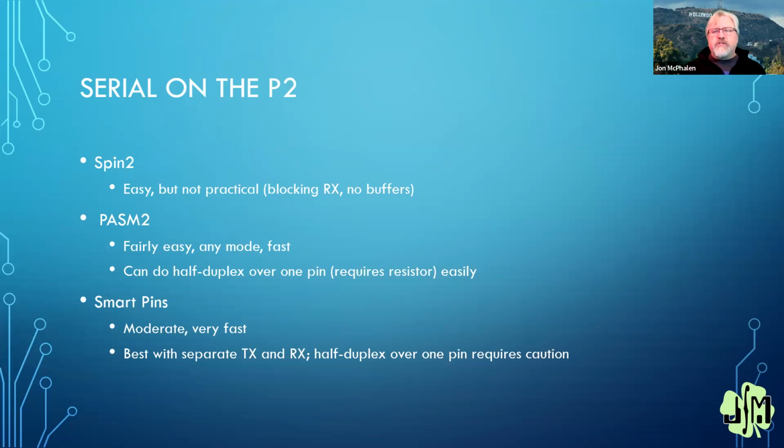It's like a smart servo that has a very wide range, and it will read back its position and all kinds of other stuff. It uses half duplex, and I just wrote a driver because John wants to use the Dynamixel in one of his projects, and I'm using the smart pins, and I didn't have any trouble with it at all. So you can use smart pins with half duplex. You just have to be aware of reconfiguring the pin in between transmissions. It's not hard to do, and I got it working quite nicely.